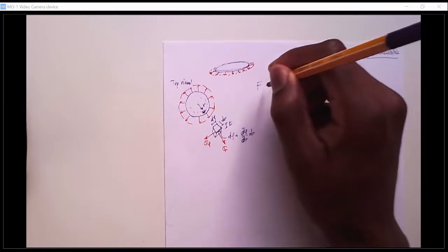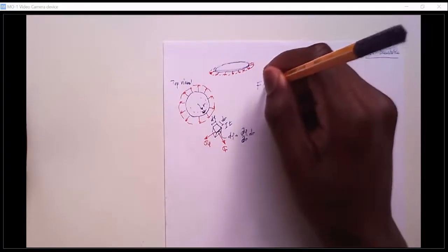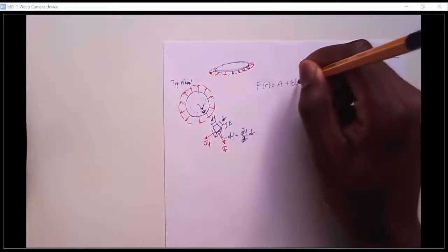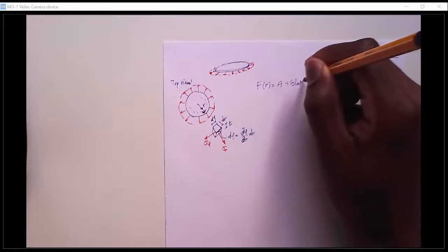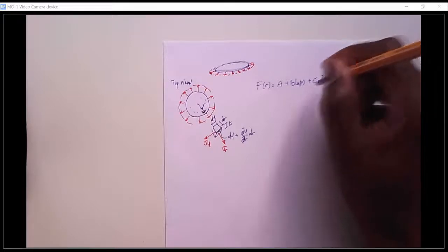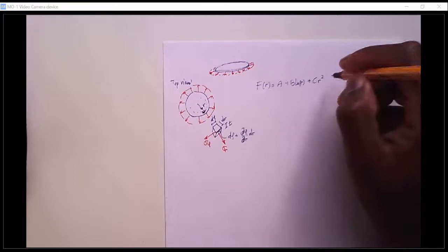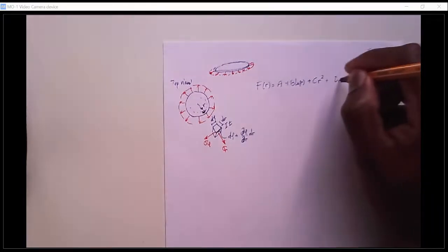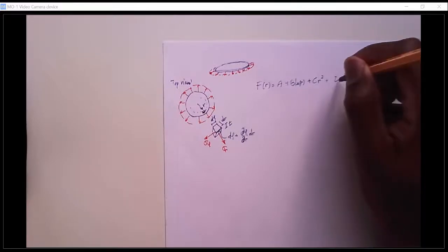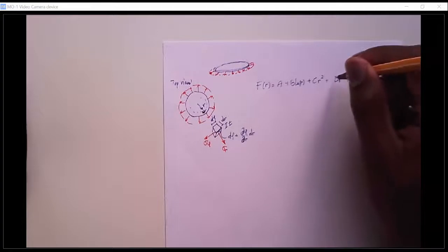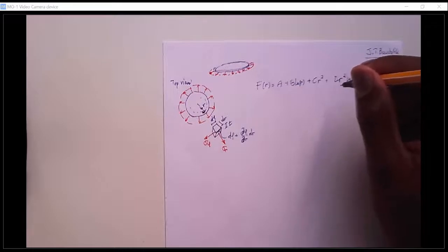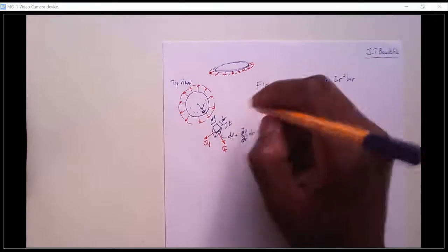It's like the Airy stress function that's given with A plus B ln r, where r is the radius, plus C times r squared. A, B, C, and G are basically constants that need to be determined. There's a last part here with G. Actually, we could cut it off already because G would need to be 0 for our stresses in the radial and circumferential direction to have finite values, but we can figure it out later together.